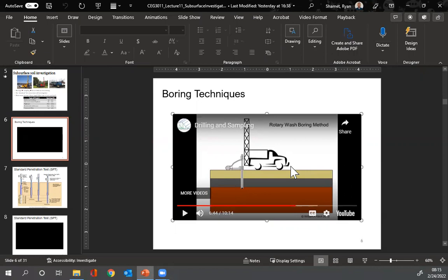So as we are drilling in Florida, which they'll talk about here in a second, the driller's mud is circulated and pushed into the hole and then back out of the hole, and that removes all the cuttings as we are drilling into the ground. So the issue though with this is this driller's mud, if we hit a loose material, like a loose sand or something pretty deep, the pressure of this driller's mud can actually disturb the sample and it can move laterally.